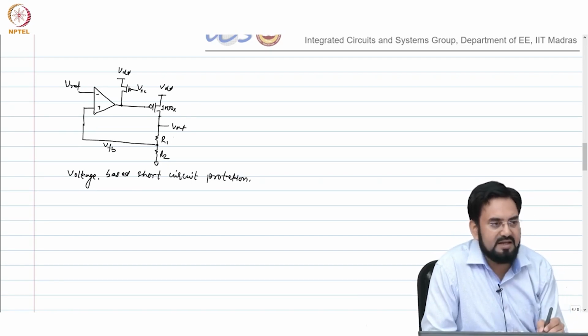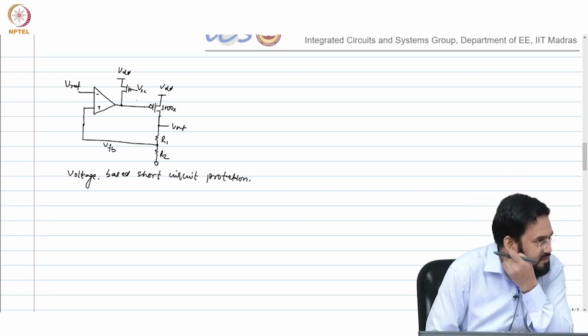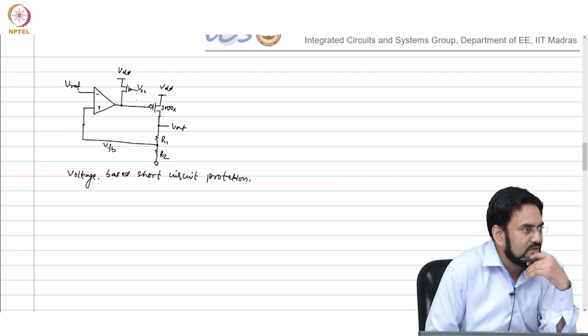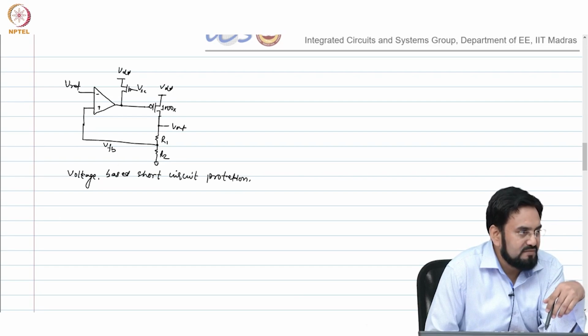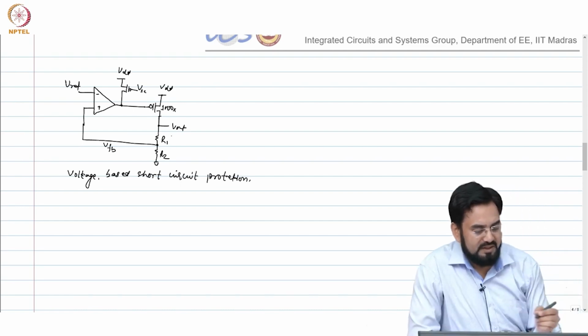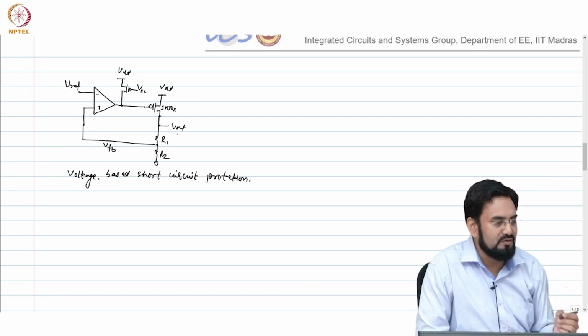Because when you start drawing high current, this will go out of regulation because your MOSFET cannot carry that much current. So your output will start going low. Ultimately it may enter into linear first, so IR drop will define your output voltage. Okay, and you haven't sized for that very low resistance, so it's quite possible your output will go low.